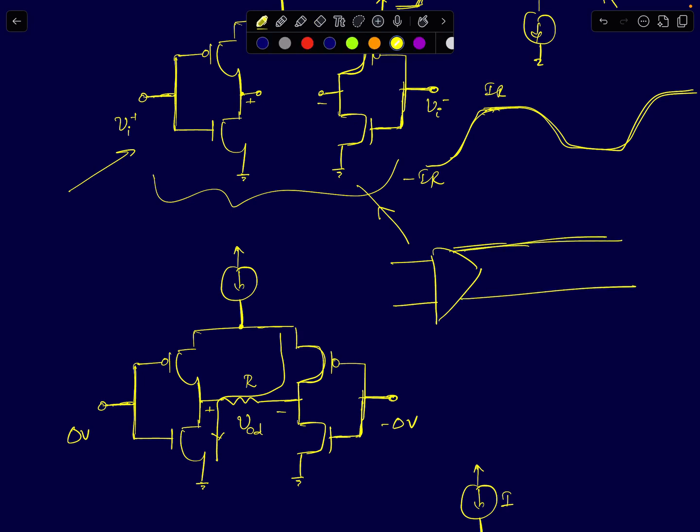and then let me show that. As this circuit is very far away, what we normally do is we place a resistor very close to the receiving circuit. Wherever this comparator is driving, we place this resistor very close to the receiving circuit.